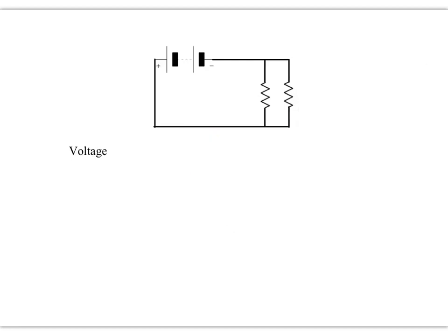The other key to understanding parallel circuits is how the voltage drops across any resistors in parallel wind up being precisely the same. And here's what I mean by this. If I start here at the battery, this right here is just a wire or a single conductive path. And even though the conductive path splits, everything I've just highlighted is all along the same wire or set of wires or conducting path.